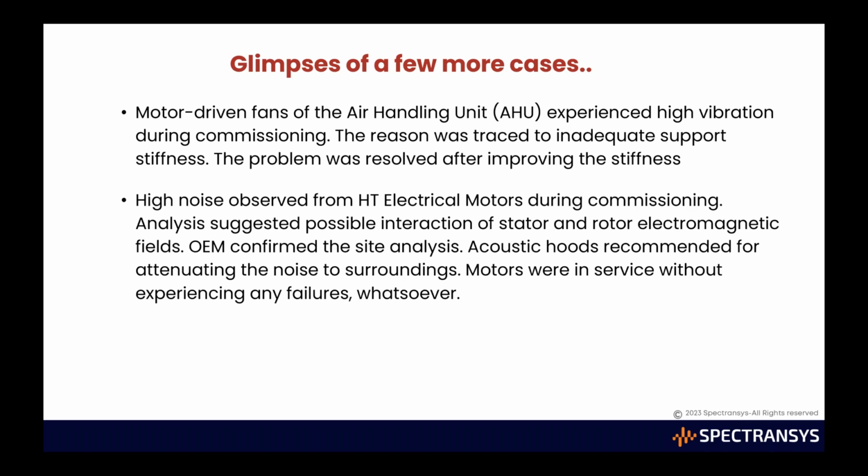Then this data was shared with the OEM, and the OEM said that this is due to a combination of stator and rotor slots that is creating the high noise level. So this cannot be easily corrected. Either you have to replace these motors or send these motors to our works and we have to rework them. It is going to be a costly affair.